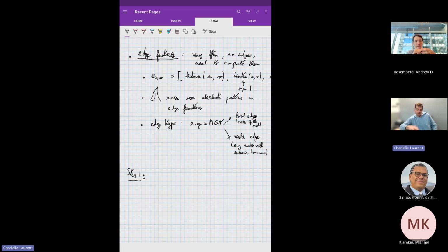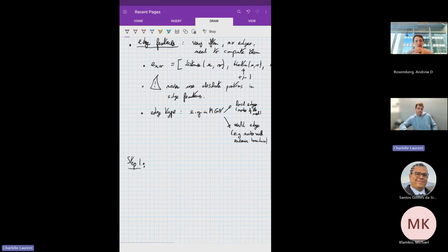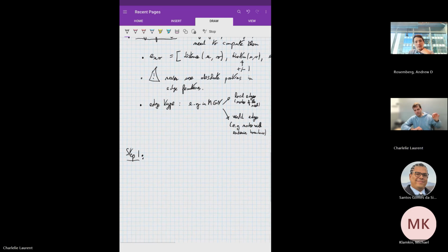So actually, it really depends on the application. For CFD applications, and for applications for which you have a mesh, the nodes of the graph will actually be the points in the mesh. They could be the centers of the cells, or, let's say if you have a tetrahedral mesh, basically the corners of each tetrahedron, or it could be the center. There is no constraint on this, but there is a one-to-one correspondence between the actual computational mesh and the nodes of the mesh graphnet.